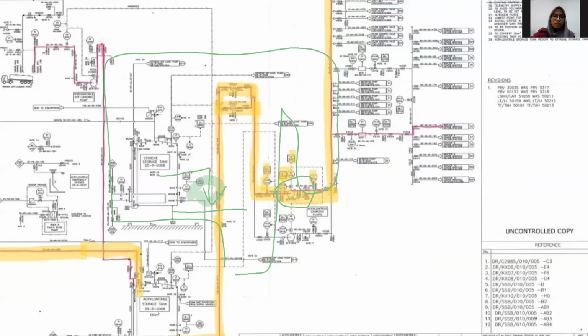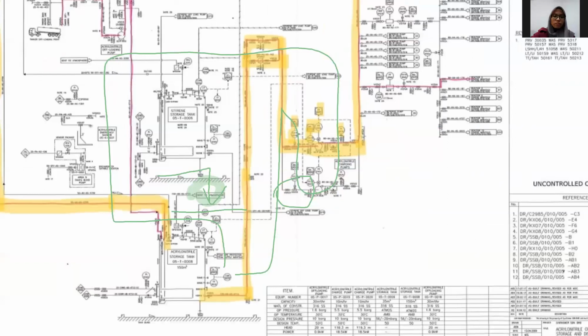Then it will drain the solution to the wastewater pond, and flush the system with nitrogen gas by connecting the hose to nozzle R of this tank, turn the remaining solution in the tank to wastewater, and close all the valves.